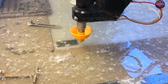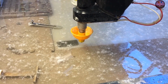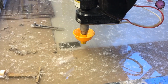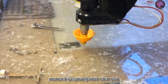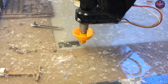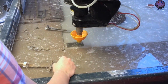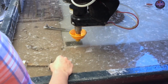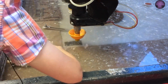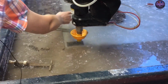The best starting position is one where the path will not interfere with any weights or the L-shaped piece or any already cut out parts. You want to make sure that the nozzle does not run into any high parts because it can break. So the right position to start your path is one where the nozzle will not interfere with any clamps, this L-shaped piece, or any weights.